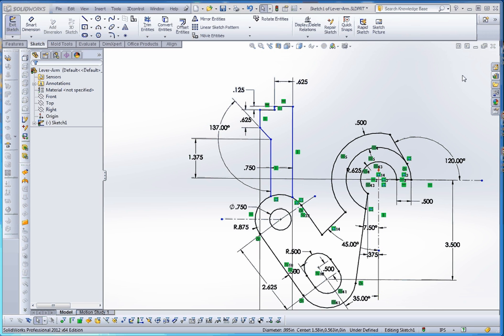So in this video I'd like to show you a little bit about some sketch elements, some symbols involved in sketch relations, and more specifically line colors associated with lines that you're going to be drawing in the sketch format. So what we have here is a sketch. It's almost fully defined. Most of it's black, some of it's blue, and of course a blue line means, that's a test question, blue line means it's not fully defined, which means it has some flexibility, has the ability to move around. A black line can't. A black arc can't. Anything that's black is fully defined and cannot move.